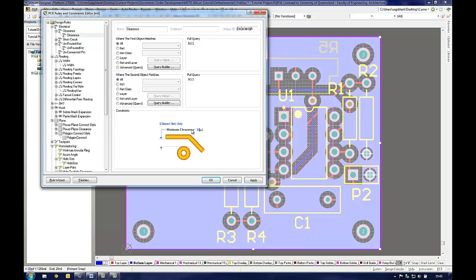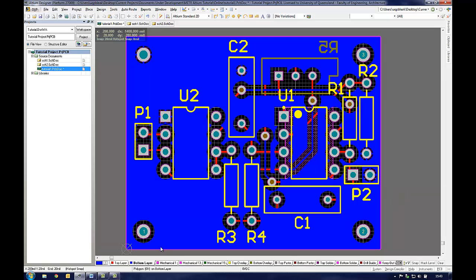The user should check the entire polygon plane to make sure that it is not fragmented and that there are no narrow necks that could possibly fuse if high currents are expected throughout the circuit. In particular, the connection surrounding the point where the ground is connected to the PCB should be checked to make sure there are strong connections. This point could be where the connector for the battery is located or the connection of the regulated power supply. If the user is happy with the ground polygon pour, then they should change the clearance constraint back to its original setting and check the PCB connection.